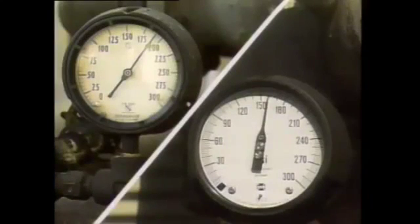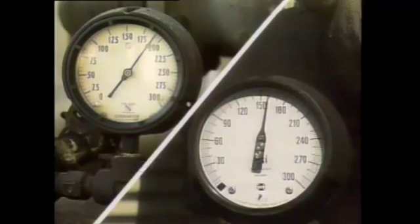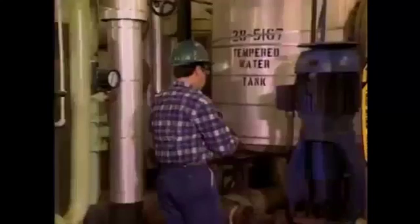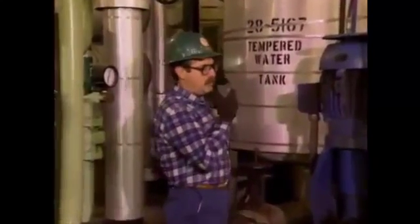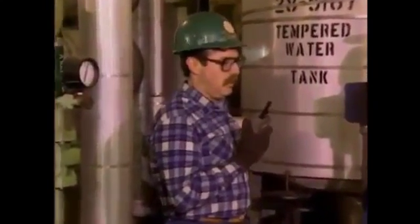Anytime there's flow through a heat exchanger, there will be a specific drop in pressure across the unit. This pressure drop is often referred to as differential pressure, or delta P. Any change in differential pressure could be an indication of a problem. As the tubes become blocked or fouled, the differential pressure will increase above the normal value. Once again, the cause of the problem should be investigated and supervisory personnel should be informed.